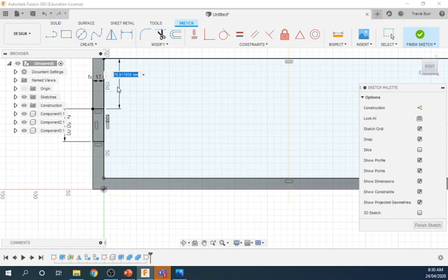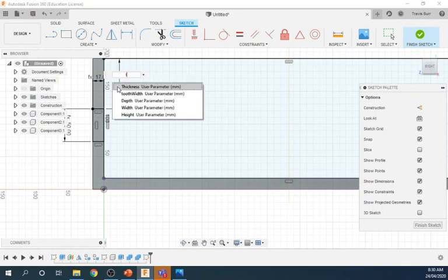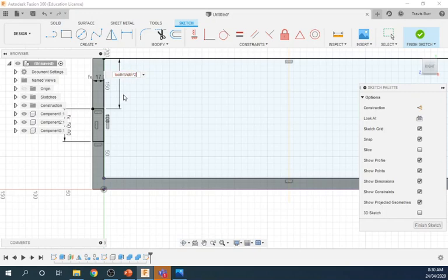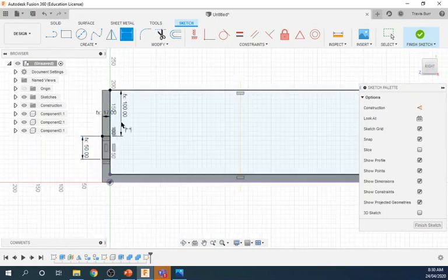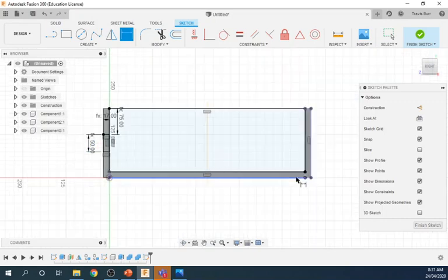And we'll set that at, again, tooth width times 2. A little lower, but I think that's okay. We could change this and center it up if we wanted. So let's say instead of times 2, let's go times 1.5. So it's still giving us a derived dimension. This will move though if the size changes. I'm not too concerned about that.